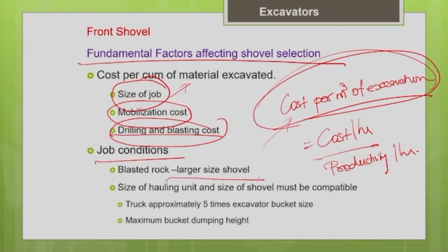I told you earlier, when you are going to handle the blasted rock, you need more effort, you need more breakout force, to loosen the material and dig it and load it into the bucket. So for that it is preferable to go for a larger size shovel which can deliver more breakout force so that it can easily do the digging operation. So for blasted rock, it is preferable to go for a larger size shovel.